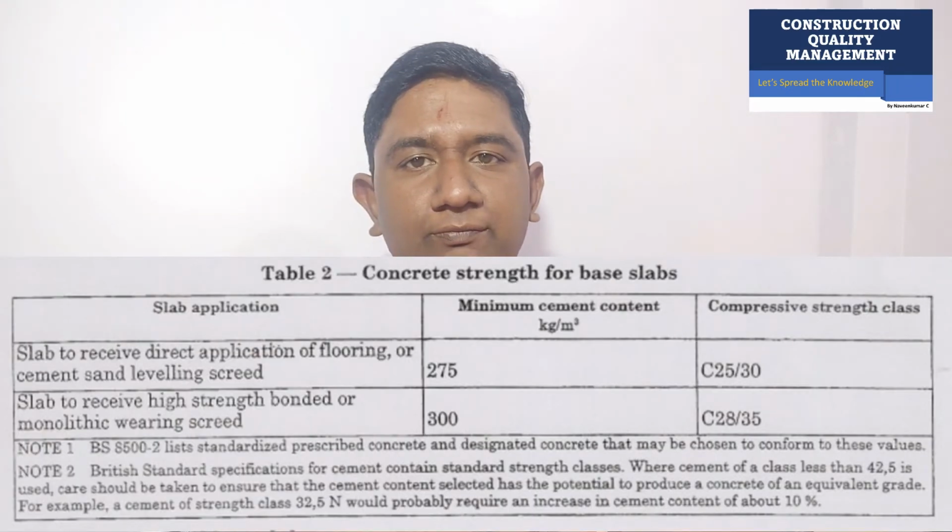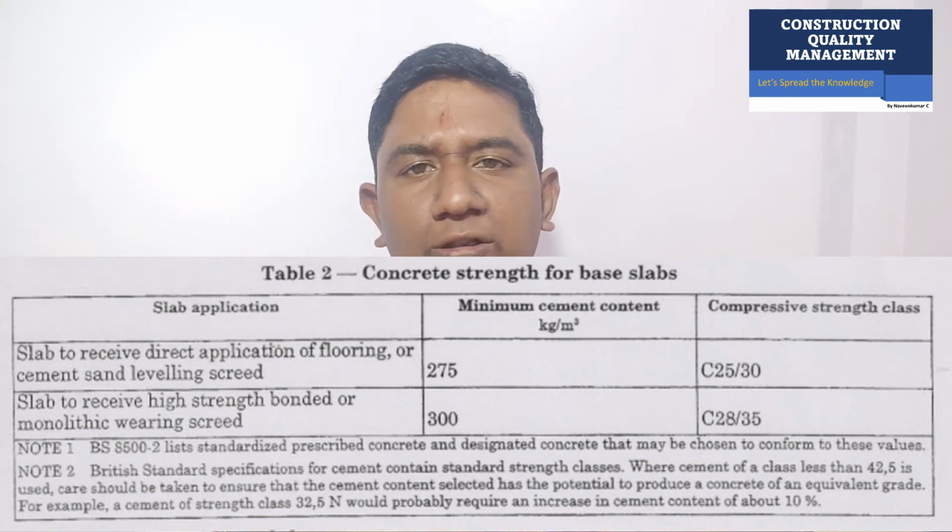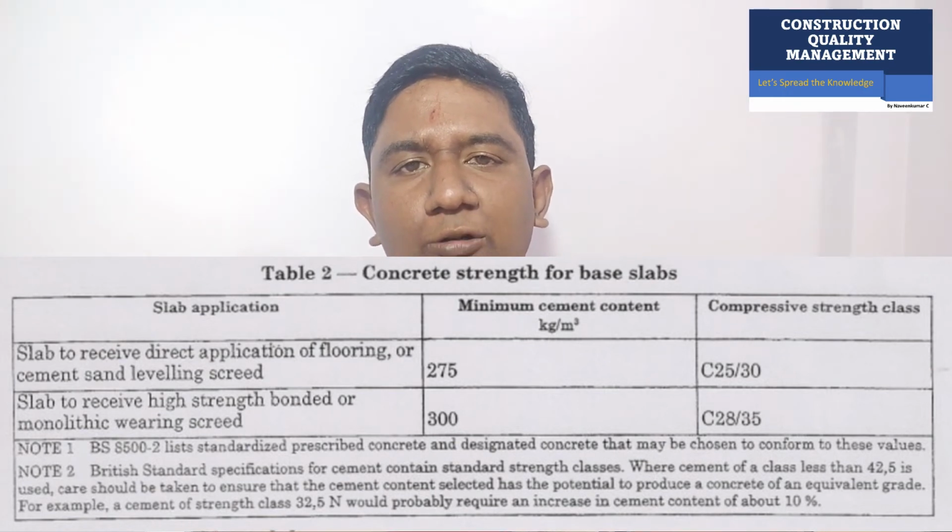Inspection in the sense, obviously you will be doing mortar or cement or sand mixture, the mix design, all those things. As per IS 8204 Part 1, the screed shall not be less than M25 grade of concrete. Whether you go with 10 mm aggregate, 6 mm aggregate, or only cement sand, irrespective of that, the minimum grade of the screed concrete shall be M25.